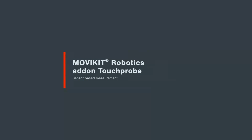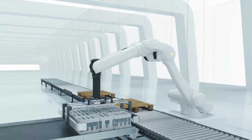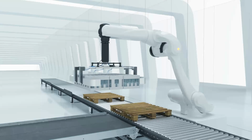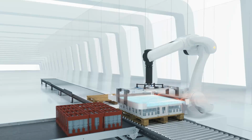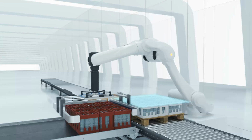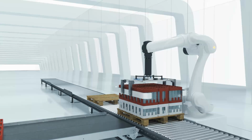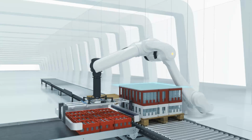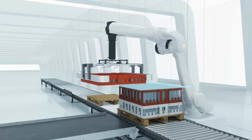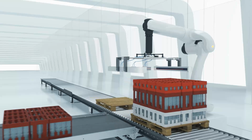With sensor-based measurement, the touch probe measurement, the exact path position at the point in time of triggering is also determined. However, sensor-based positioning is not initiated directly. Instead, the Cartesian touch probe position, shown here as the blue level, can be used as the target point for the next placement procedure.